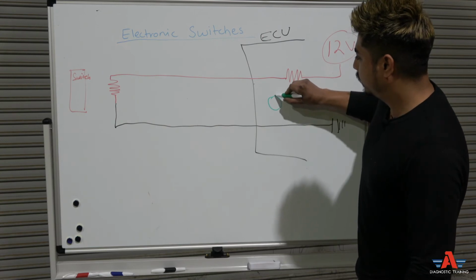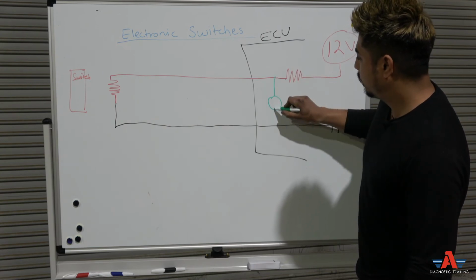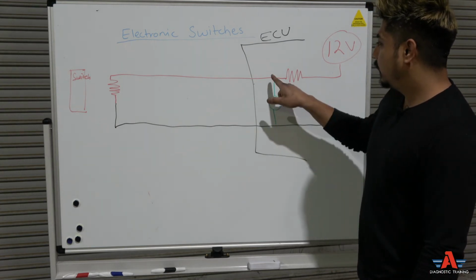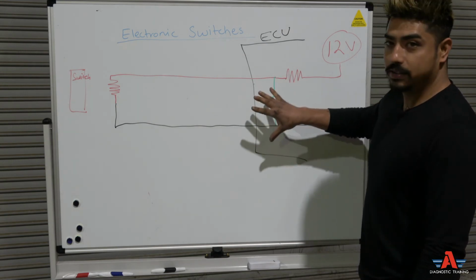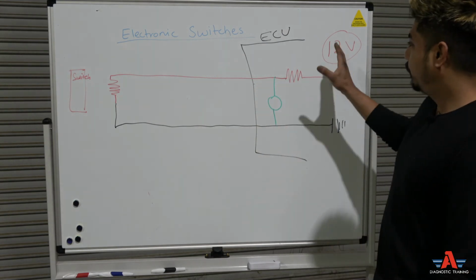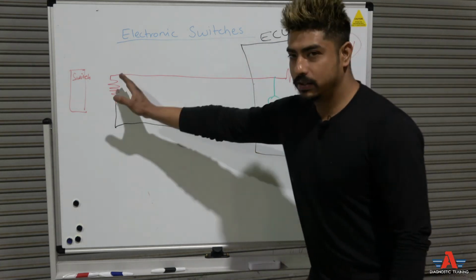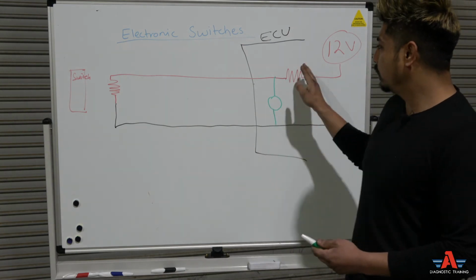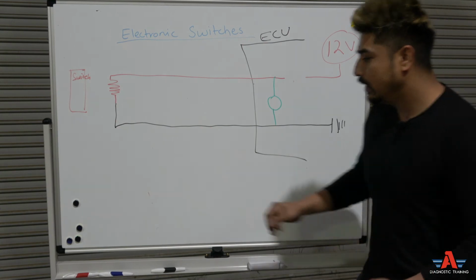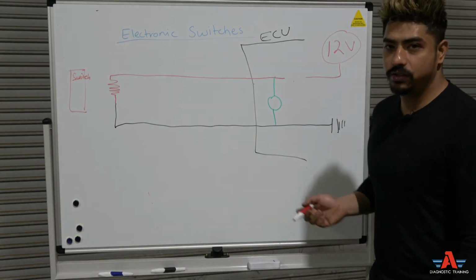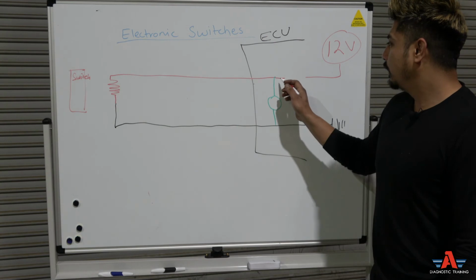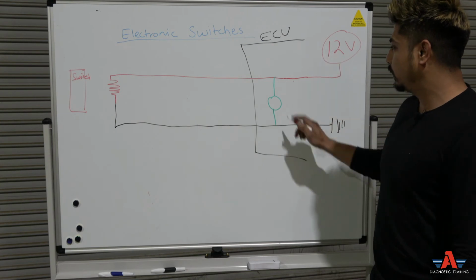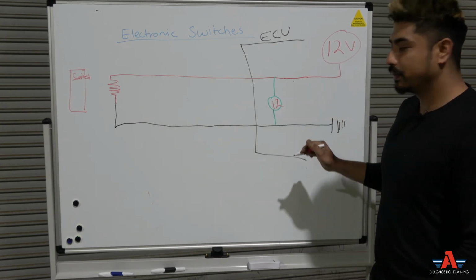So the digital multimeter is going to have one lead going to here and one lead going to earth, okay? Now, this is going to read any voltages in the legs where it's connected. So they put this between 2 resistors because it needs to know the voltage changes. If there is no resistor here, you will never see the voltage change, okay? So if you connect this to the battery directly, it's going to see 12 volt all the time, okay?